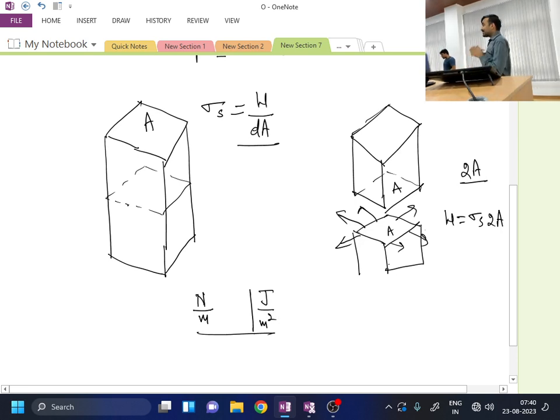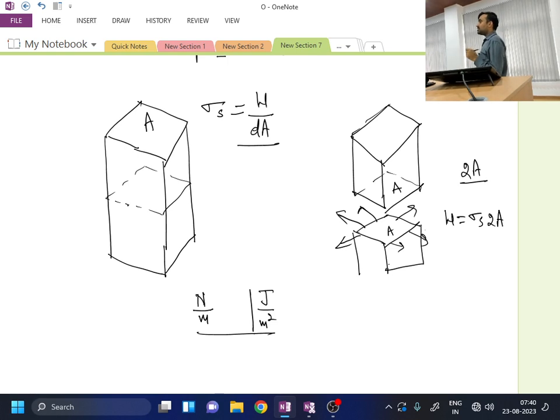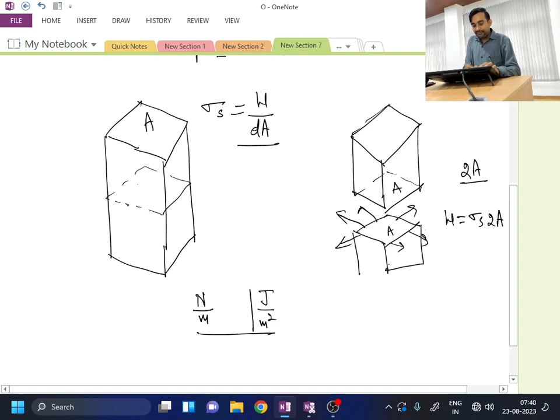So if we now consider surface tension, it is not the property of a fluid, but it is the property of a liquid and the other surrounding fluid combination. Okay, how? For example, when we talk about surface tension, if I am referring to the bulk of the fluid, at the bulk of the fluid there will not be any occurrence of surface tension.